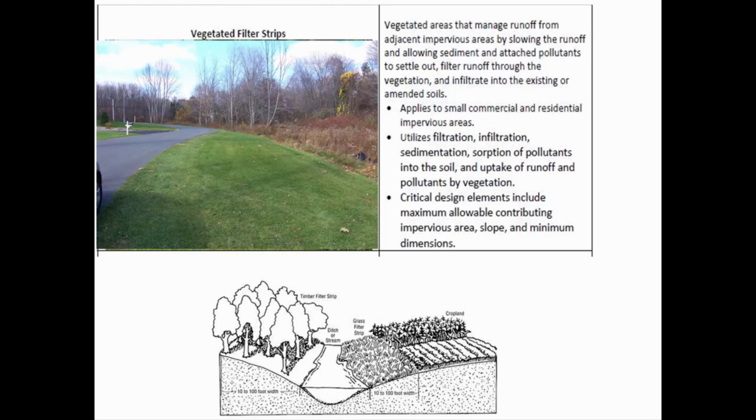We just have to think a little bit differently, and the goal is always to try and delay water's arrival to its ultimate outfall. And by outfall, I mean maybe the water's going to a creek, maybe it's going to the Ohio River or to a lake. We just always want to slow water down when there's a storm, and as much as possible encourage infiltration.